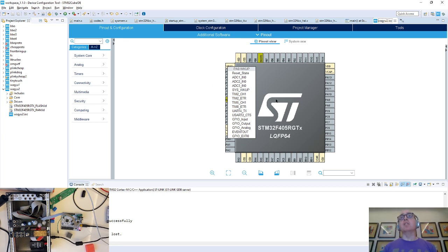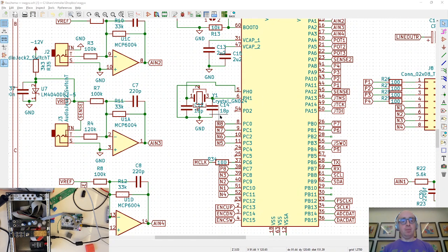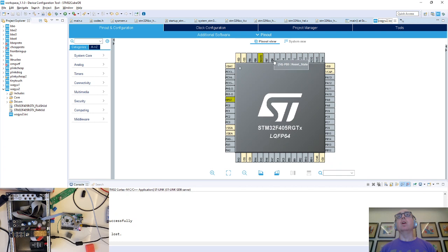Right, so what I like about this is that for every chip, you can basically find out that this pin, PA0, can do ADC inputs, timers, UARTs, USART. So when I was designing the schematic here, I had an instance of CubeIDE open, and I basically set things up. So I know that PB6 and 7, pins 58 and 59, I decided were going to be a UART. So let's just bung them in. So basically I'm saying I want those pins to be the UART.